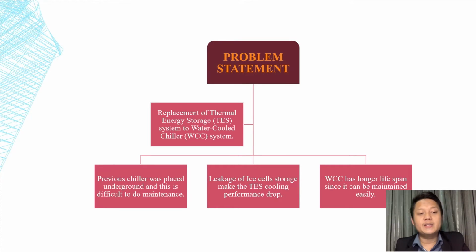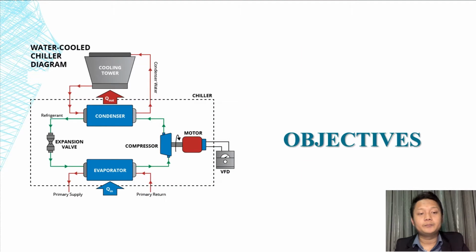The previous chiller was placed underground and this made maintenance difficult. Leakage of the ice cell storage made the thermal energy storage cooling performance drop. The water-cooled chiller has a longer lifespan since it can be maintained easily.